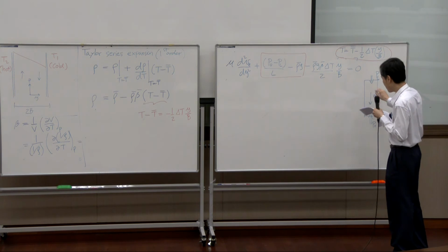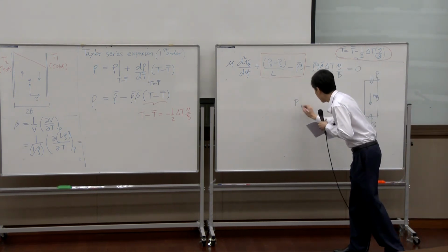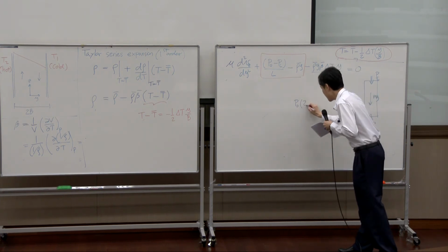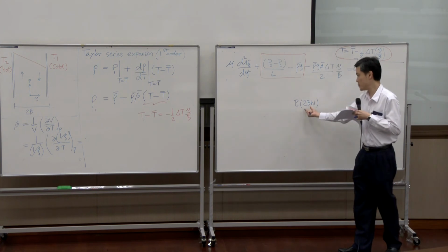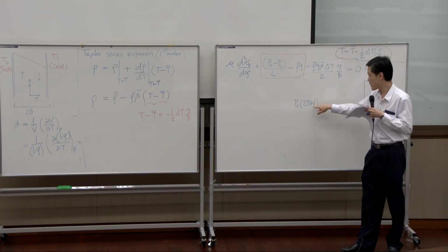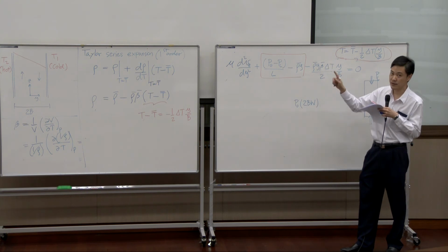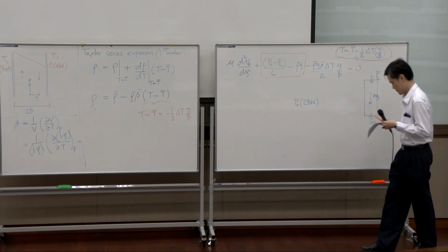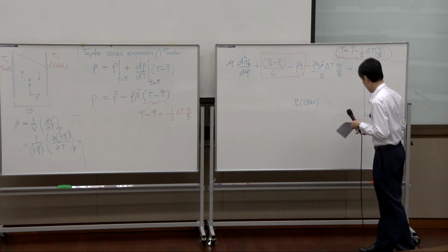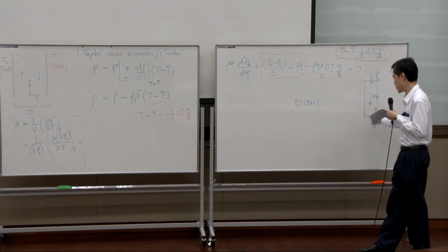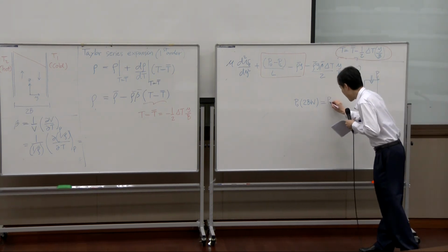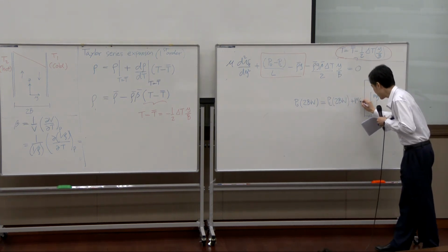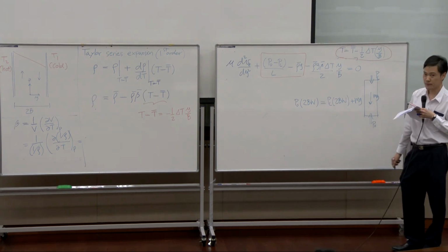If I do the force balance, I will get that the force pushing up, P0 times the cross-section area 2b, which is the whole width, multiplied by the distance perpendicular to the screen, should equal the force pushing down plus mg. Right?